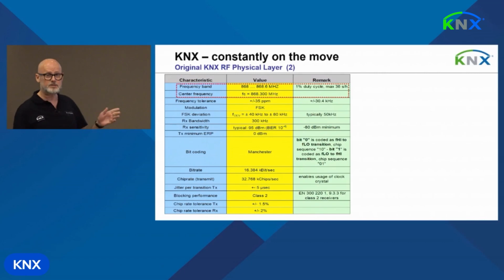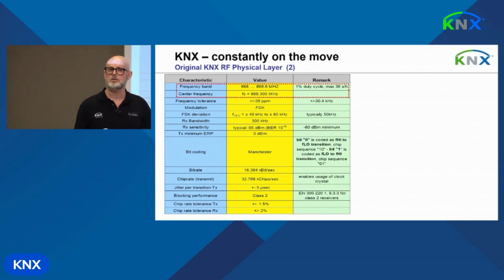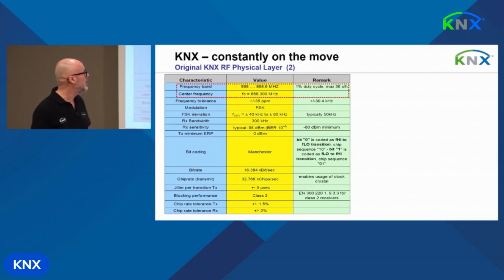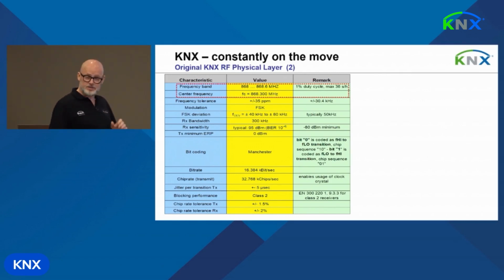So, as I have said, the frequency band is 868 till 868.6 with a 1% duty cycle. That means that a device may, per hour, transmit a maximum of 36 seconds, not more. The center frequency being 868.3 megahertz.